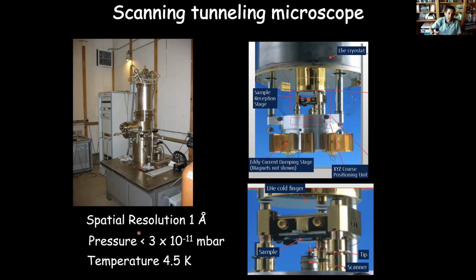So we can stay over a region for a long period of time. The low temperature gives us very good energy resolution so that we can essentially see things that are occurring on the sort of millivolt, millielectron volt scale. And the trick here that we need to do is that in this previous slide, you can see these scale bars. These devices are generally on the order of 5 to 10 microns in size. And so we need to position our tip onto the sample here with about a 5 micron precision.